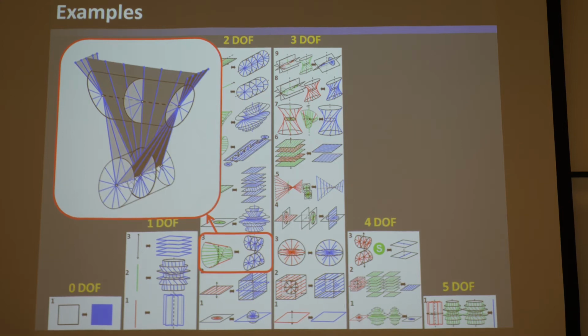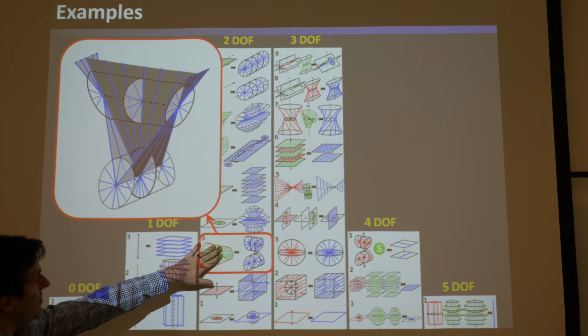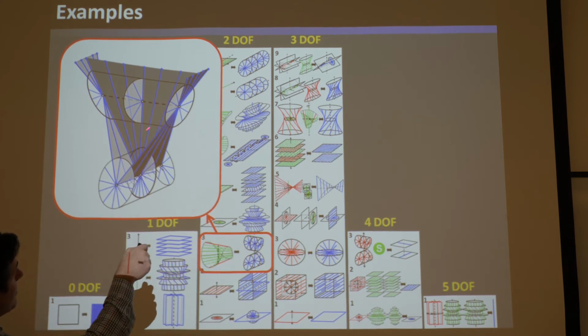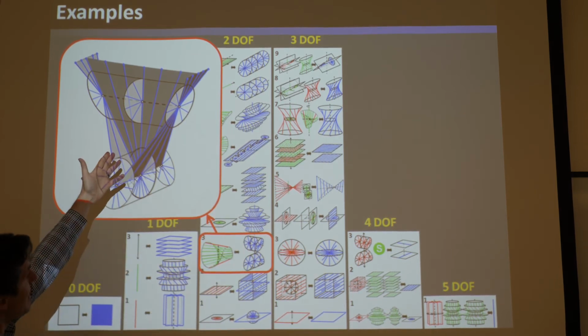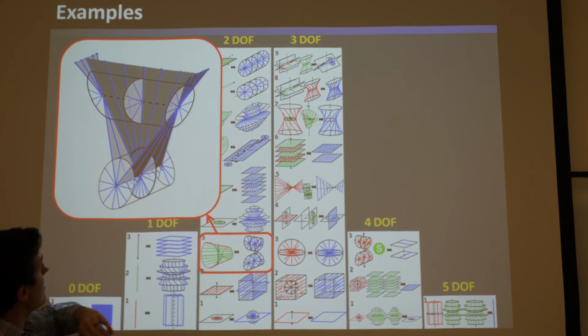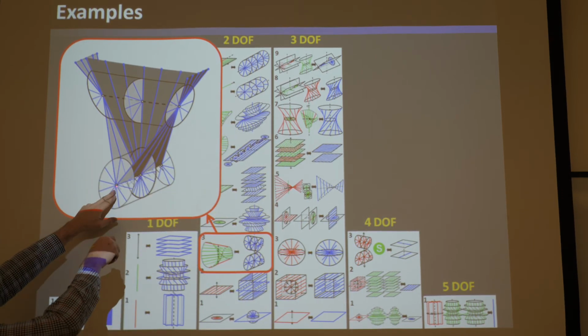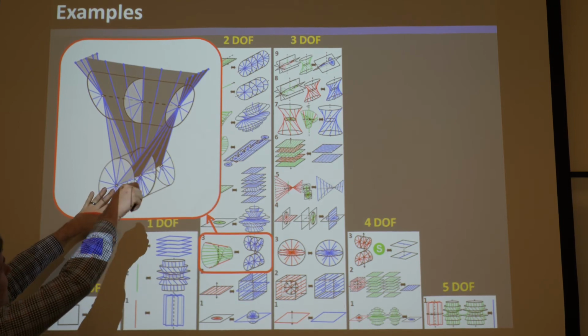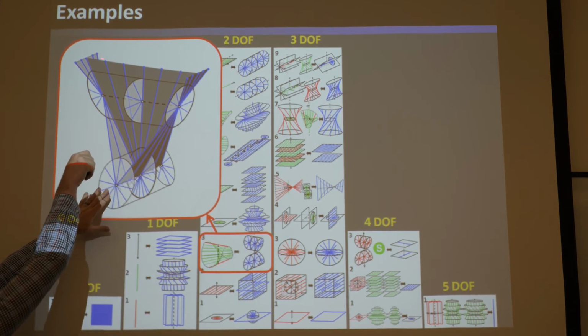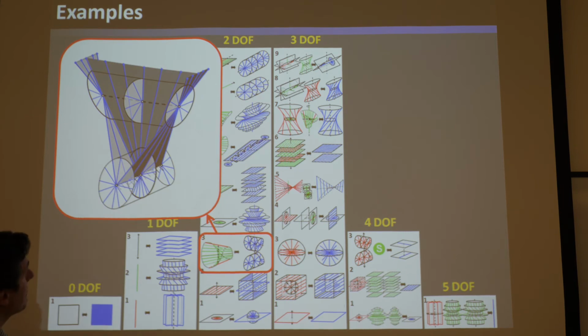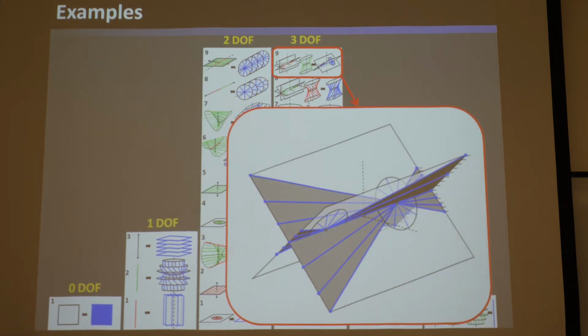Okay, so other ones, and I'm going to stop talking about the condition here just in the interest of time, but if you want to achieve some really interesting freedom spaces, this is a 2D freedom space. Here is a flexible element that lies within this constraint space, as you see here. We've oriented it the same as there. So, here would be a ground, you can see the hatching there, or a stage, and here would be ground or a stage on top. It would attach on top there. And for those attachment points, you can see this satisfies the two conditions, and it would achieve a rotation through this dotted axis and a rotation down here.